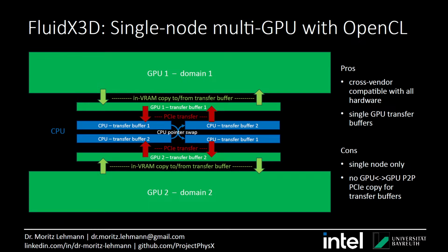And it would have to do this every time step, of course, right? Yes, and in every time step, it cuts the simulation box into two parts, and where they touch, there's an interface, and some data has to be transferred across the interface in every time step. So the entire box is like 10 gigabytes in size, and this interface area is like 10 megabytes. That is this transfer buffer that gets extracted first within VRAM and then copied over PCI Express twice.